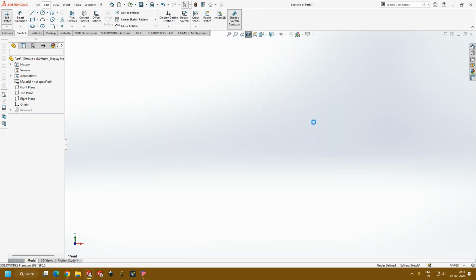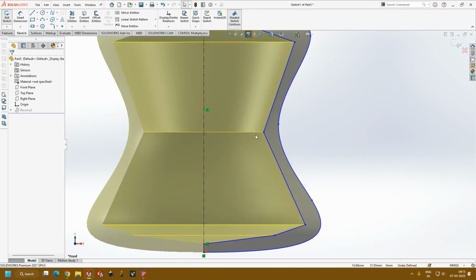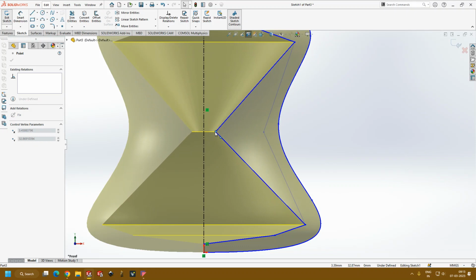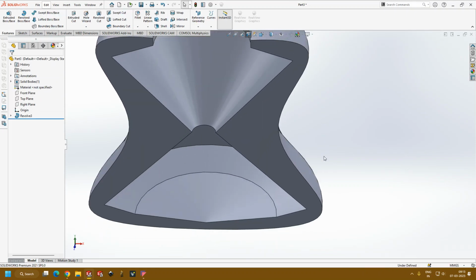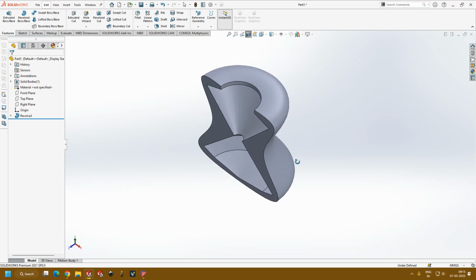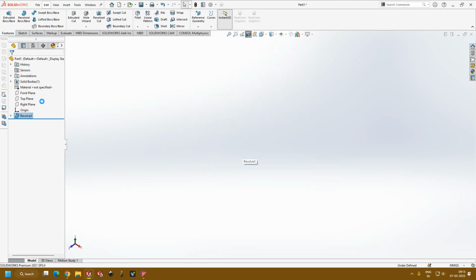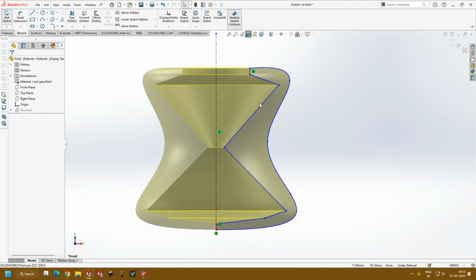And similarly, if I'm changing the sketch, so if I'm moving this, you can see my sharpness. And then if I exit, you can see this sharpness. So the only thing you require in this is a closed sketch. So you make it by offset or you make it by line, it doesn't matter. Only thing you require is a closed sketch.